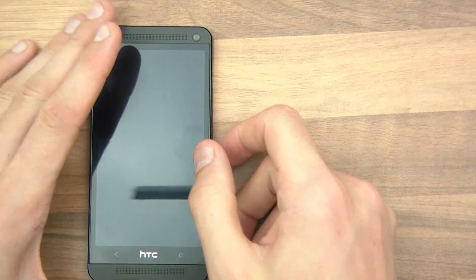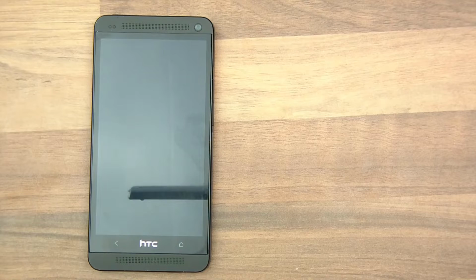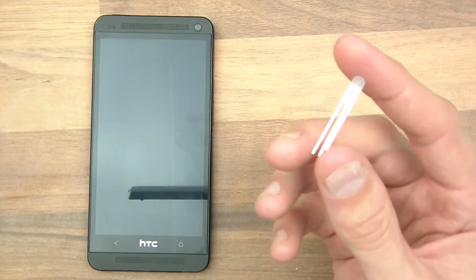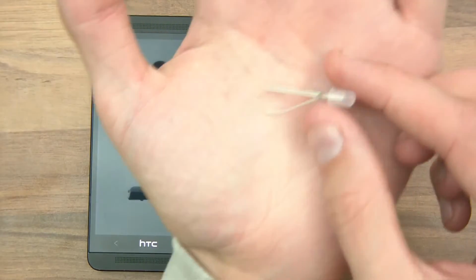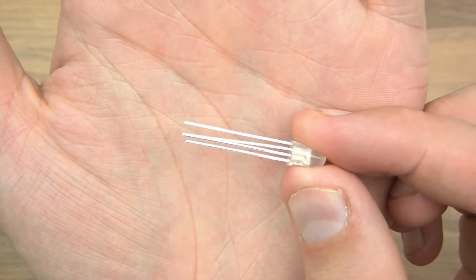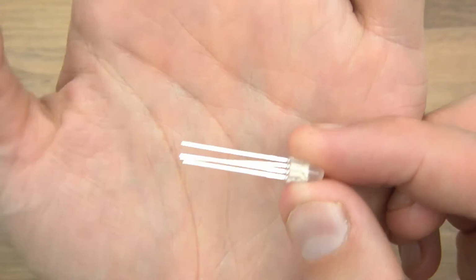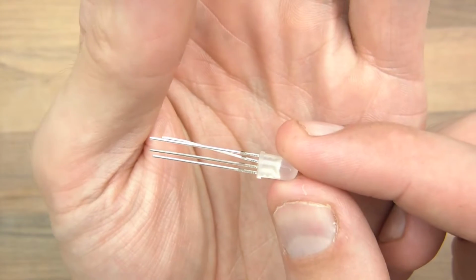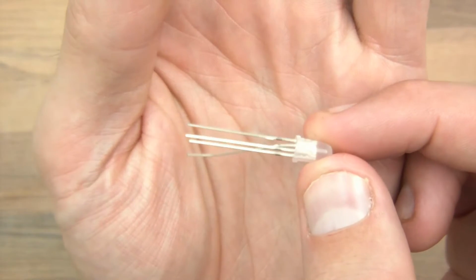I'm going to install an app on it, which Reyax have provided, and I'm also going to get this LED here, along with some other components. You can see this is a 4-pin LED, and it's 4 pins because one of them is a cathode and the other 3 are anodes for different coloured LEDs, if you like, which are in this one LED.